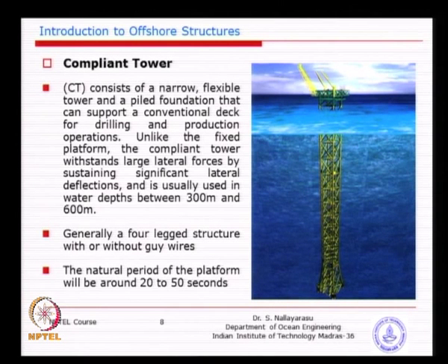Otherwise, it is designed as a compliant tower. So, what is the meaning of compliant? Basically, when the wave forces act on the structure, it is not going to resist as a rigid structure, it is going to get displaced. So, there is a relative motion between the wave and the structure, allowing large bending. What we get is a little bit of relief from the loading coming from the waves, number one. But then how do we sustain that motion? We change the equipment at the top to suit such a large displacement from the sea waves.